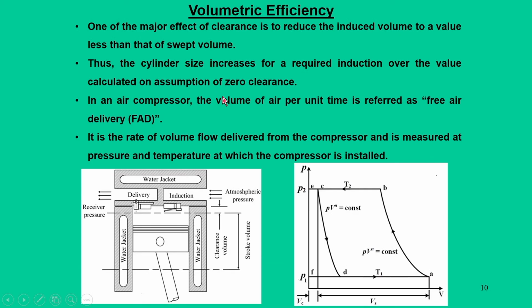So, that is how we quantify volumetric efficiency and what its significance is, and all these things we are going to discuss here. One of the major effects of clearance is to reduce the induced volume to a value less than that of the swept volume. We can see that initially this volume was Vs, now this volume becomes Vm minus Vd. So, this Vs is now reduced to Vm minus Vd. See, the cylinder size increases for a required induction over a value calculated under zero clearance. So, if that is the case, then the cylinder size must increase.